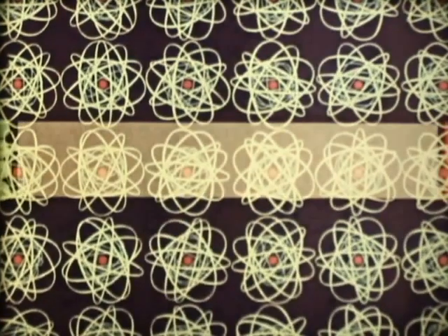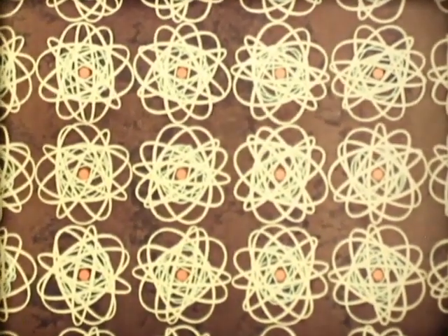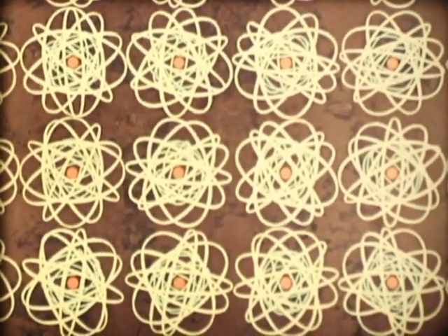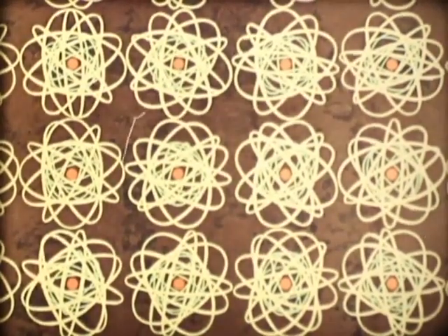This non-conducting signal plate behaves in a similar way to a charged capacitor. That is, it may be considered to comprise a number of extremely small capacitors. At the left, each capacitor has an excess of negatively charged electrons, and at the right, a shortage of electrons, making it positive. In between is the photoconductive layer, which is, like any material, composed of atoms. The nuclei are shown in red, and the electrons in orbit around them in green.